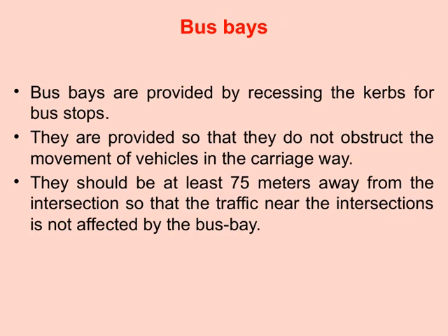Let's talk about bus bays. These are created by recessing the curbs at bus stops, which essentially means carving out a section of the curb to allow buses to pull in without blocking the main roadway. The main purpose of this design is to ensure that buses can stop and pick up or drop off passengers smoothly, without obstructing the flow of traffic behind them.